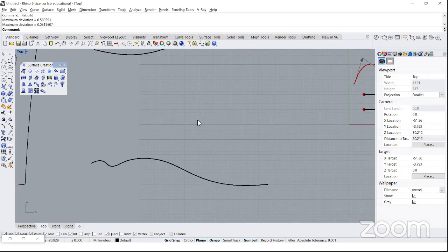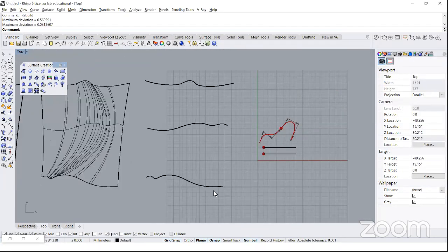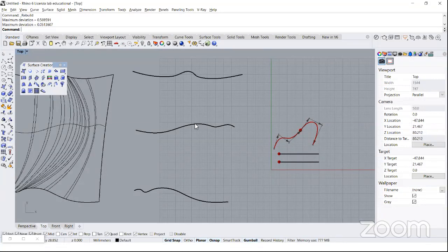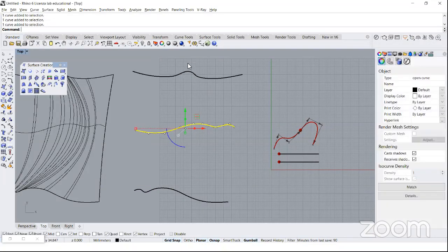and I take the new section as the section that I'm going to use for the loft. So if you do this analytically, like I'm doing, you should rebuild this one and this one, okay? But I also see that this curve is smoother than this one. And this one as well is smoother than this one. So I suppose that 30 control points are enough also for this one and this one.